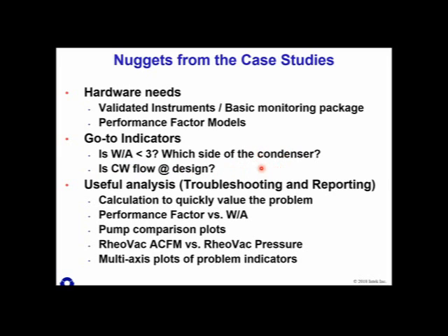And if it's not one of those, or if this one doesn't indicate macrofouling, then it's probably scaling or something like that. So by process of elimination, very quickly you can cover all of the things that can go wrong with the condenser. This is number one. That's number two. And then by process of elimination, you probably have a scaling issue or an air binding issue.